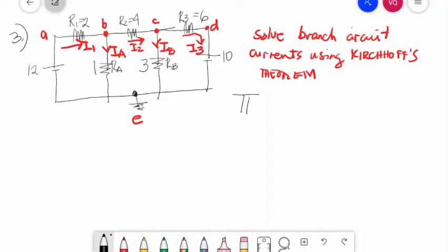To minimize, you combine all these conductors into one common node, which is your letter E. We will take first the KCL equations of node B and C. And also, for checking, you can get the KCL equation at node E. So you will have 3 KCL equations: node B, node C, and node E.